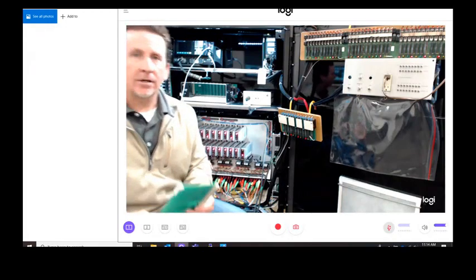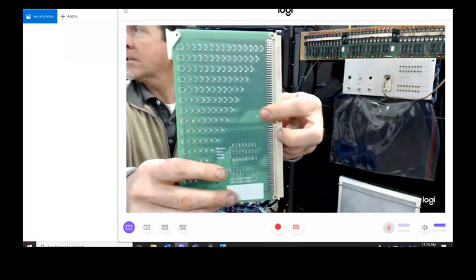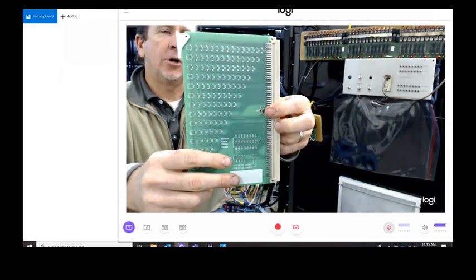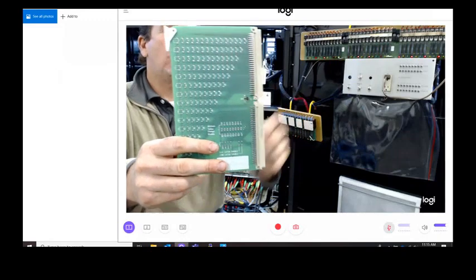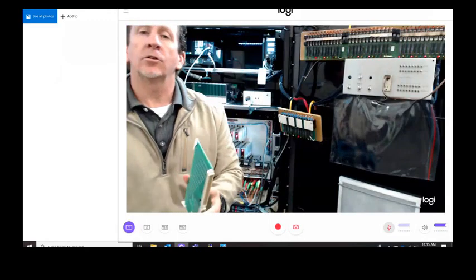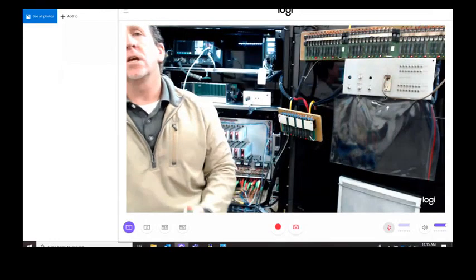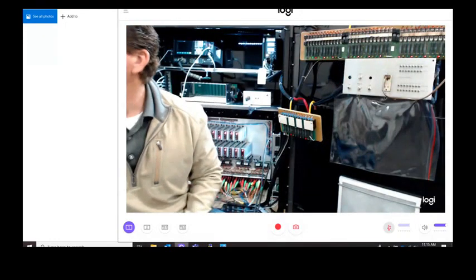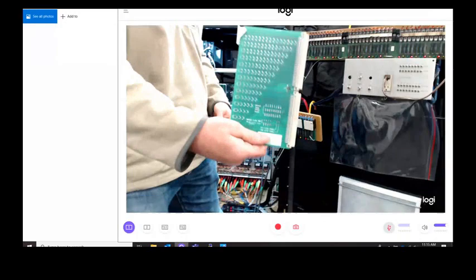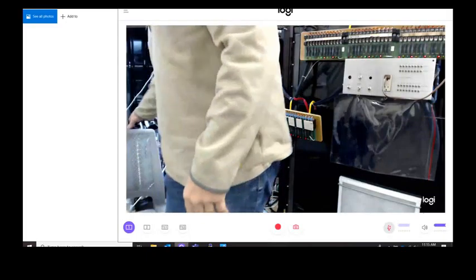One thing you have to be leery of, I'll show you over here, is in an MMU2, you'll notice this little transistor, this little black guy right here. If you don't have that on there and you plug in, so the old cards didn't have this, if you plug an old card into a new MMU2, you won't be able to get that functionality out of it. It'll work for non-flashing yellow arrow, but if you want the flashing yellow arrow functionality, you have to have that little transistor on there. So just keep in mind that they're interchangeable to a point. I don't have an older card, but basically it looks exactly the same. It just doesn't have the little transistor on it. Keep that in mind while I'm talking about MMUs right now.